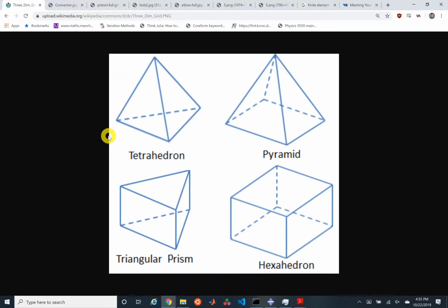You can imagine if you have these hexahedral elements, the innermost ring's edge closest to the center is going to be a little bit shorter than the edge that's further away from the center. And at the center, there's going to be essentially a zero length edge, and that's effectively this wedge element. That's typically where they're used.